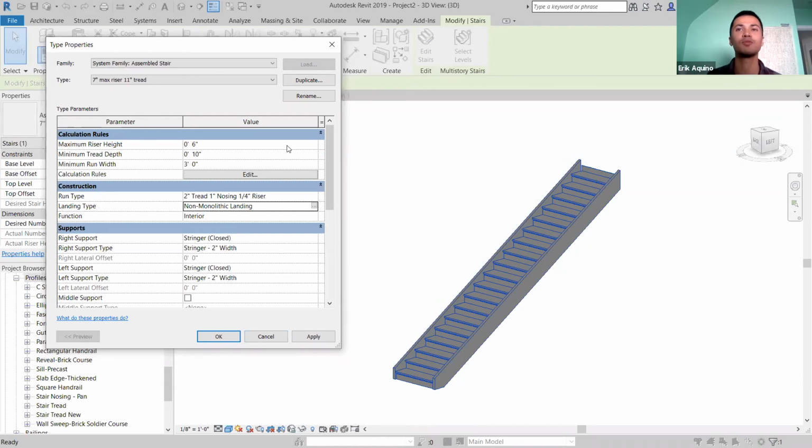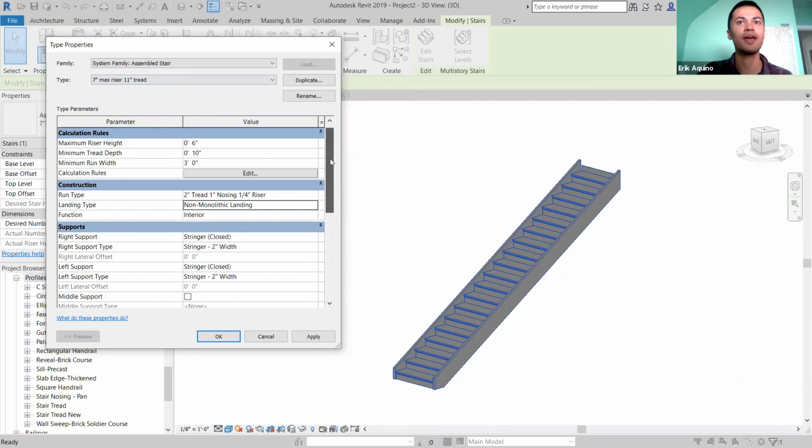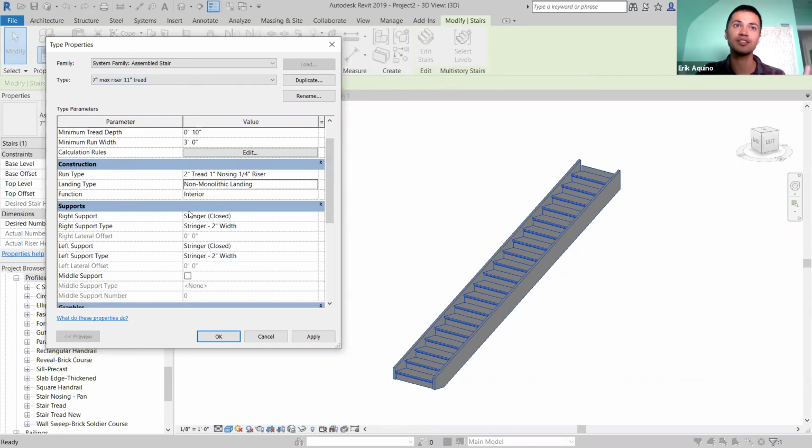And as I mentioned before in the walls section, if you do modify something that's existing, make sure that you duplicate it first, not like how I did right now. Duplicate it first so that you retain the original, and then you have this new one that you could fiddle around with.